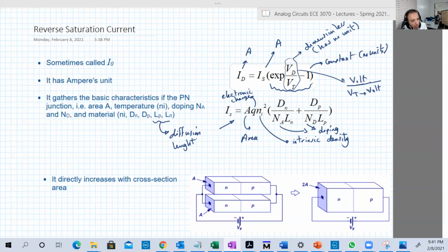Each one will have its own Ln and Lp, and it's basically the average length, in meters, that the carrier will flow before its recombination. For example, when holes move under forward bias from P to N, some of them will make it along the way until they reach the negative terminal of the battery, and some of them will recombine inside the N-type region with other electrons.